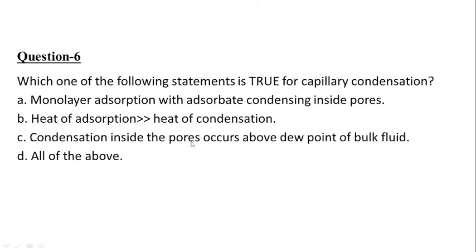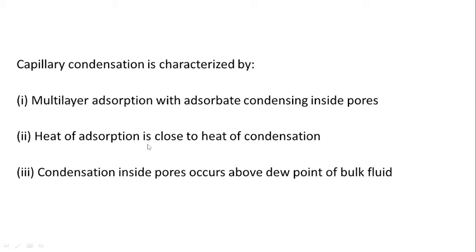So the answer for question 6 is C. Capillary condensation is characterized by these 3 points: multilayer adsorption with adsorbate condensing inside pores, heat of adsorption close to heat of condensation, then condensation inside pores occurs above dew point of bulk fluid.